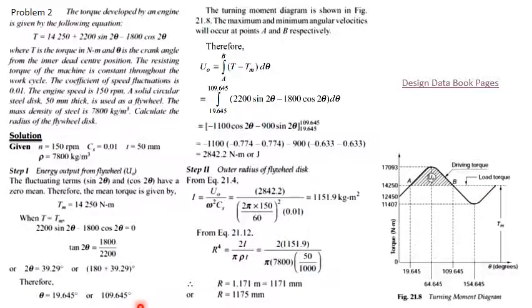So if we see these two values A and B, where the driving torque is going to increase, in this period the value of torque is greater than the mean torque provided by the motor. Therefore in this area there will be the fluctuation of energy. The energy will go down, and this amount of energy has to be taken care of by the flywheel.